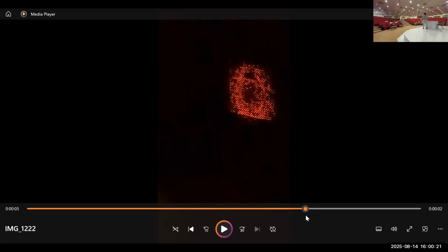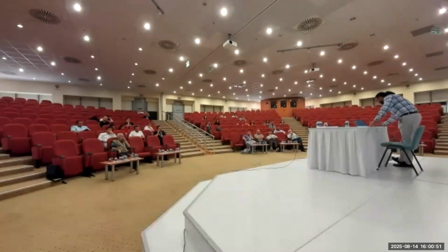So basically, the RF is strong enough to light up these, to make them glow from a distance. The RF is stronger than the threshold of the neon bulbs. So this is kind of a TM01. We were happy when we saw this radiation pattern. I can show you. Every day this changes, on the same device. It's really challenging, but let me show you another radiation pattern.